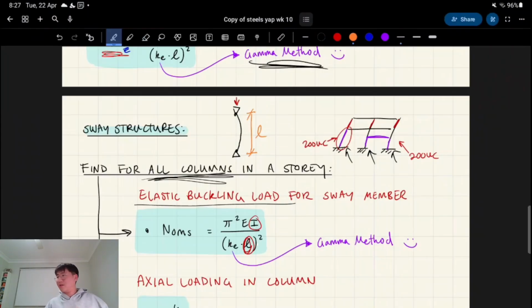Imagine a stick the length of a pen, and you push down on it. It's going to be pretty stiff, it's not really going to buckle so much. But imagine doing the same thing with a stick the size of your room. It's not going to take very much to cause that to break through buckling.